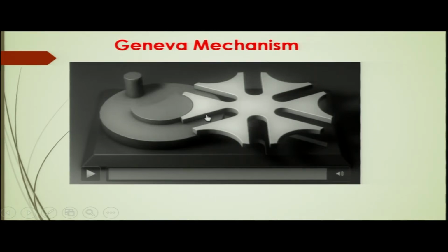Then when it is entering into the slot and coming out, during that time the sub assembly on that plate, let us say that plate is driven by the Geneva mechanism like this, that plate will be rotated, that is indexed from one position to another position, and another sub assembly is coming to the particular position where the processing will be performed. So, in those kinds of movements, the Geneva mechanism is very effective in transmitting the power.